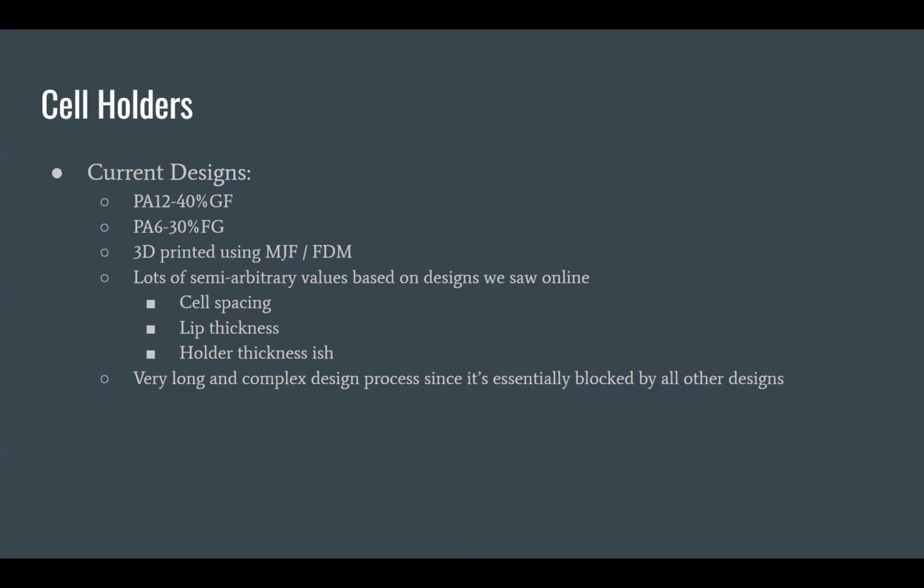So basically their guidance is you should design it in accordance with good engineering disciplines. You shouldn't have a micron of space between your cells if they're going to arc, because eventually you're going to get them close enough that with humid air and if salt accumulates on the surface and all those things, you can get a perfect storm where it's going to arc and then cause problems.